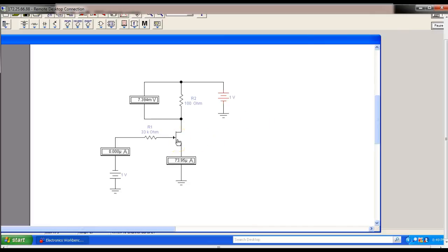But what's really neat is we're using an electronic workbench to literally come in and watch what the pinch-off voltage is. And also, we know what the cutoff voltage is now. So the cutoff voltage is when we put a voltage gate to source that literally cuts off the channel. The pinch-off voltage is the voltage where the drain voltage does not control the current flow anymore. What controls the current flow is the voltage gate source, which is pretty neat.